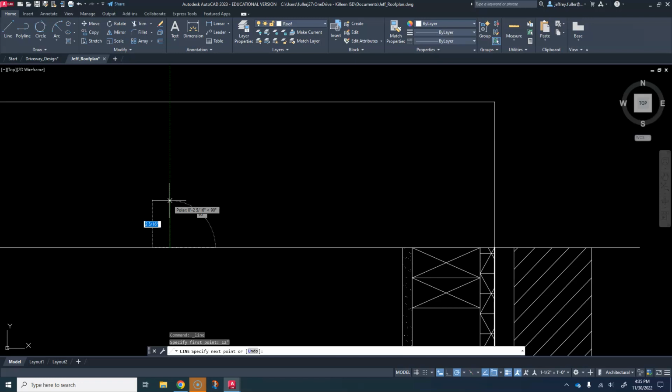So you hear people talking about a term called rise over run. You need to remember this term, rise over run. That means the roof rise, the slope itself, is going to go up 6 inches within a 12-inch horizontal space. So I'm going to draw this line 6 inches, and I drew it crooked.